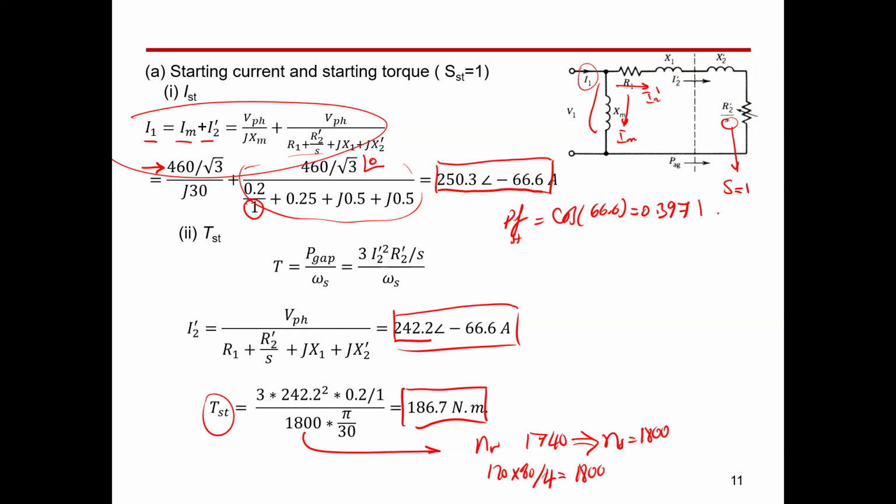All the time, the induction motor power factor is lagging. You remember, guys, in the synchronous machine, we had the option to control the motor power factor because there is internal excitation that we can use to control the power factor. But in induction motor, we don't have that. So the power factor of induction motor is not controlled, and all the time is going to be lagging.